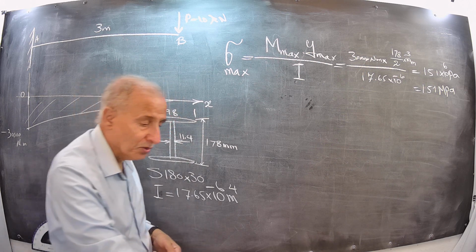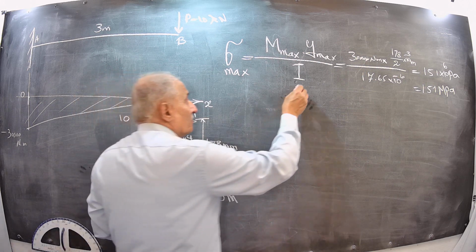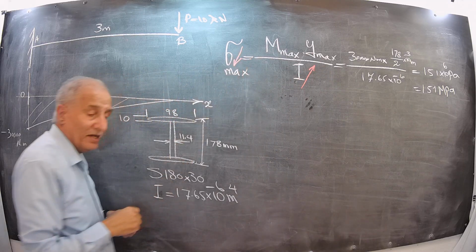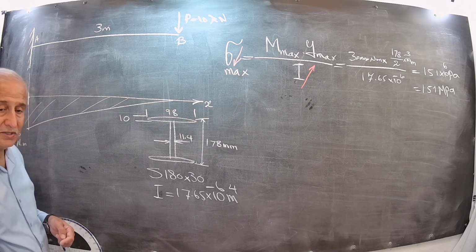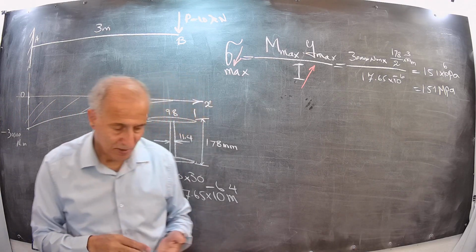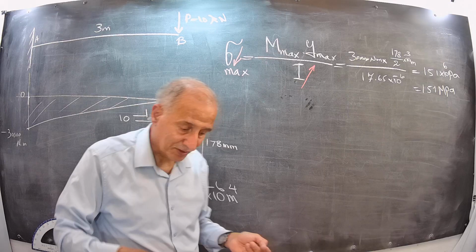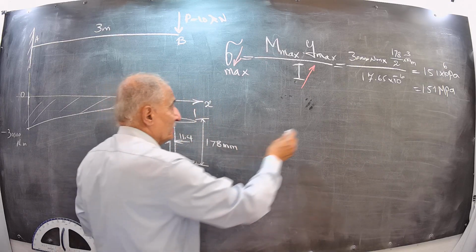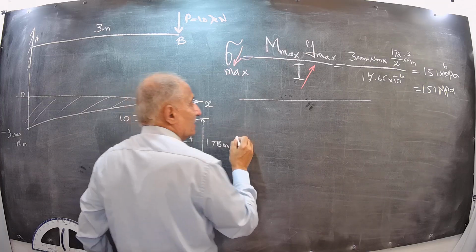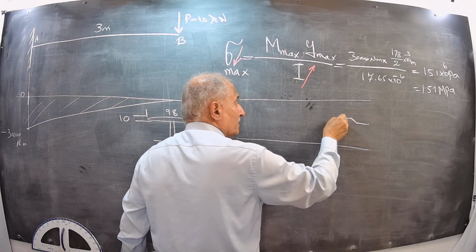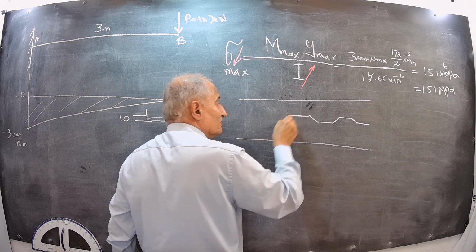By increasing I, you can decrease the stress. How can I increase I? Castellated beam? Yes, it's one of the methods. Then I consider this beam and I give it to a machine. The machine cuts it into 2 pieces.